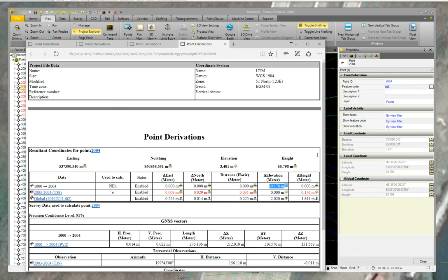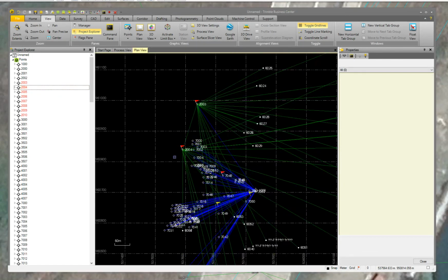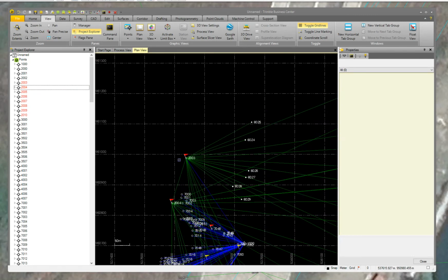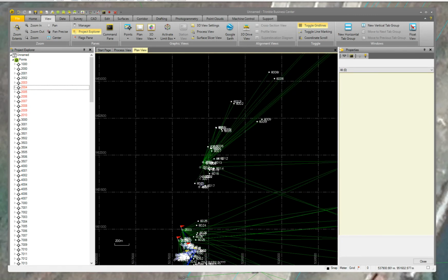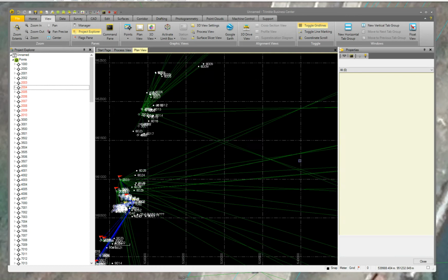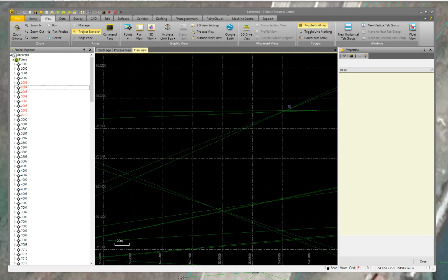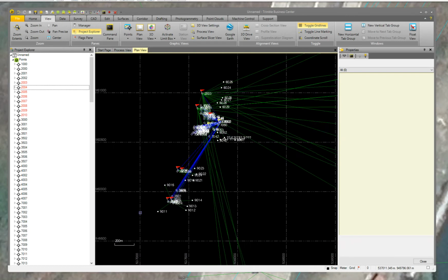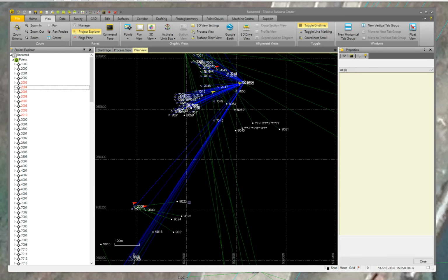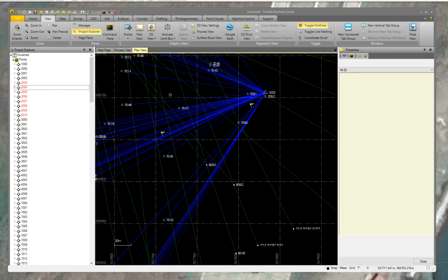So it's hard to know where that's coming from, but there's a consistent vertical error here, it seems. Sometimes it's 3 decimeters, sometimes it's 1.5, but there's something slightly off there. But otherwise, the other data kind of looks good. You can see you've got some intersection points out here. You've got some obstructions that you shot close in. So it's a good start to the data.